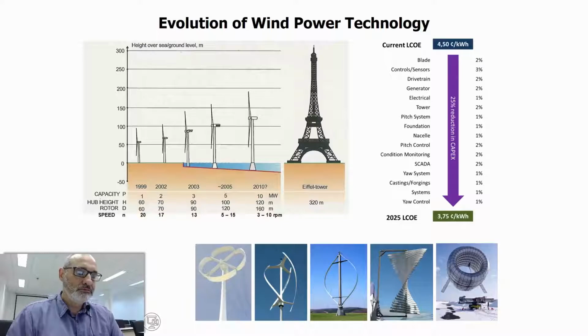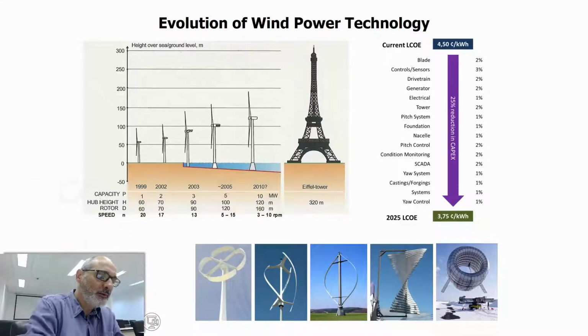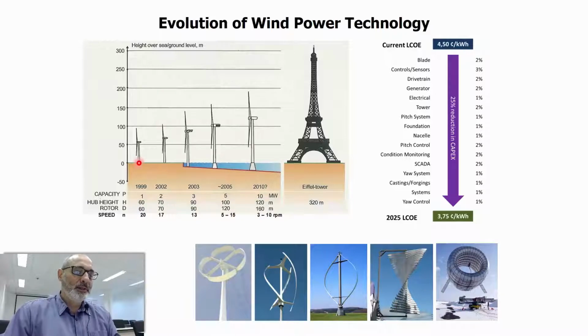Some words about wind turbines. Some details here to depict a scenario. First, the longer the blade, the more efficient the windmill, because you decrease these wingtip vortices. So the tendency over the years is to have bigger and bigger windmills. But after 100 meters, you start having problems building and installing these windmills, because you have to produce these blades and travel through the countryside, where you have small roads.